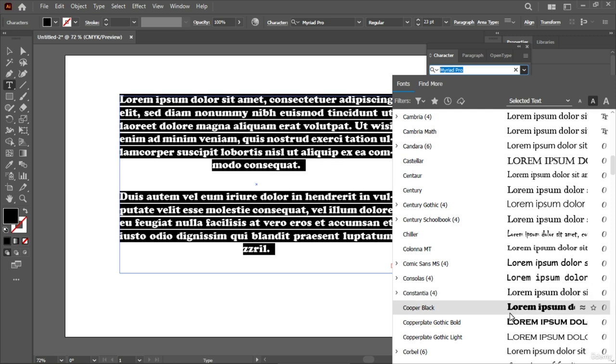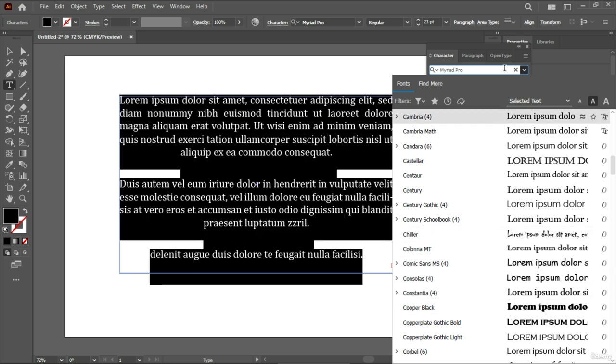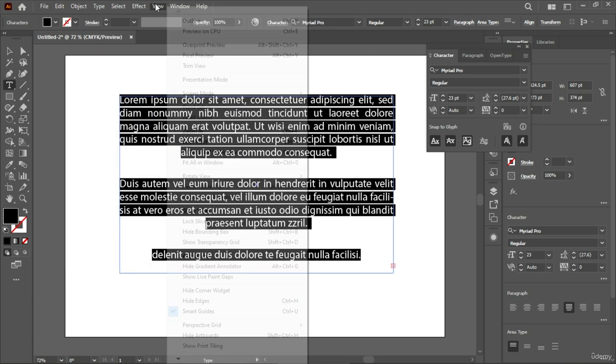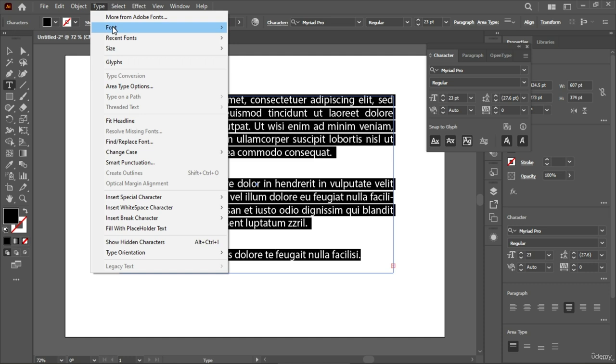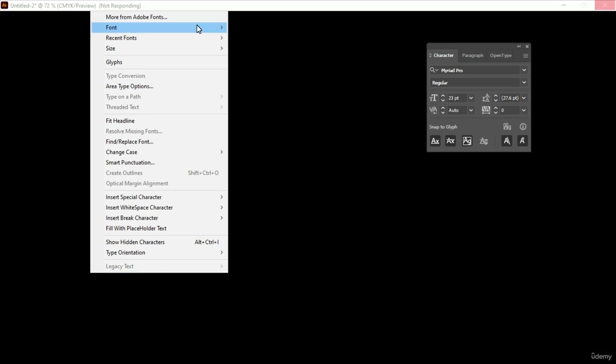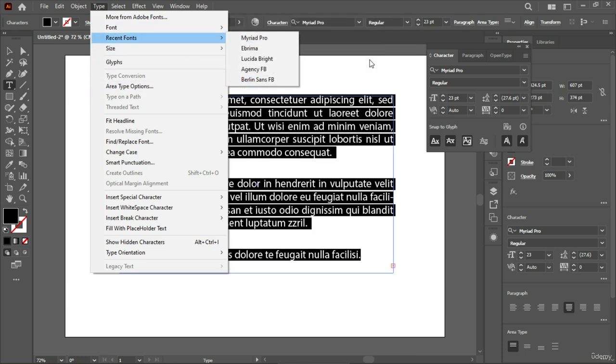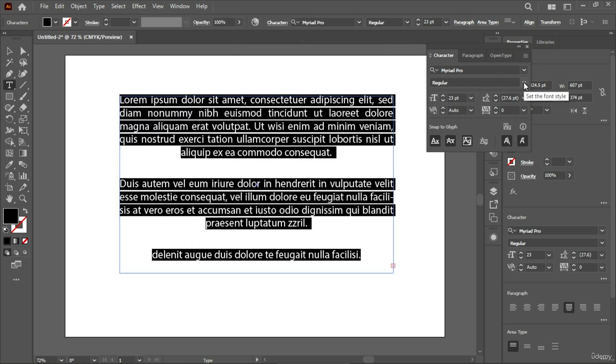Now that we're done with that part, let's go over here and explain what each of these options will do. First one over here is set leading. Now, if I click that, you can see that after each line, there's a space between them. This one increases the space or decreases it according to your need. All right. After that, we have set the tracking for selected characters. Let's say I increase it. You can see that after each word, the spaces are increasing, and it's making our paragraph a bit bigger. All right. As you can see, this is how it works. Let's turn it back to default.